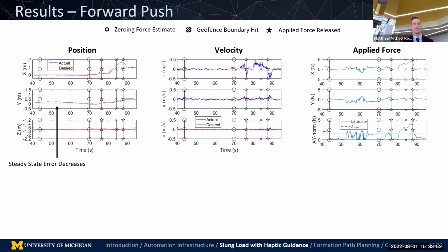If we notice in the very beginning, which was not pictured, the system took off and it was given time to settle. So that was to allow us to test the PI controller. It was tuned very conservatively such that the user wouldn't accidentally push the system and it would jerk back some. So what is actually happening here is we allow the system to settle, the I term picks up, and it can reduce the error to actually go to its set point.